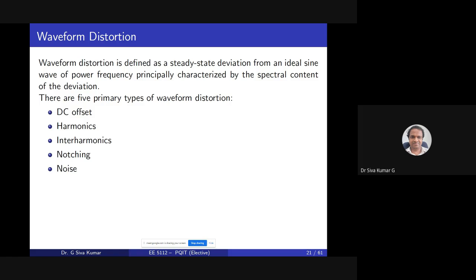For any kind of hardware, any experiment or any prototype which you are going to develop, you should have a proper grounding, where the unwanted signals, with other frequency components of very large magnitude, are removed.